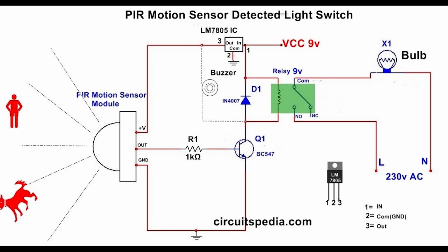This motion sensor works around 5 volts, so that is a great voltage for any common purposes. So this is a regulated 5 volt supply we have. According to this diagram, they use an LM7805 linear regulator IC because their voltage source is 9 volts, so they want to get a stable 5 volt voltage. According to the data sheet of the LM7805 IC, it is rated for 1 amp.